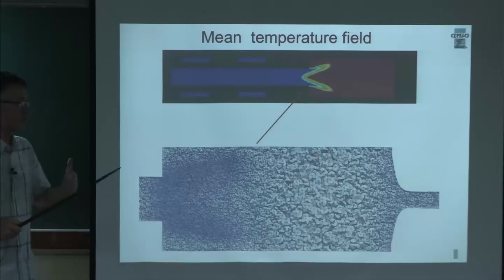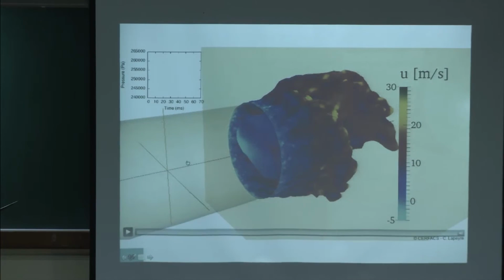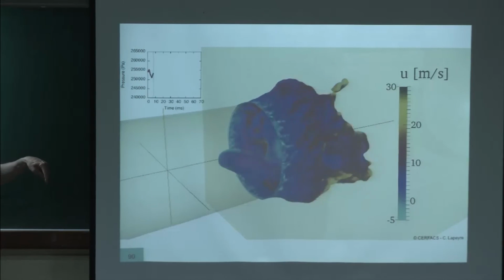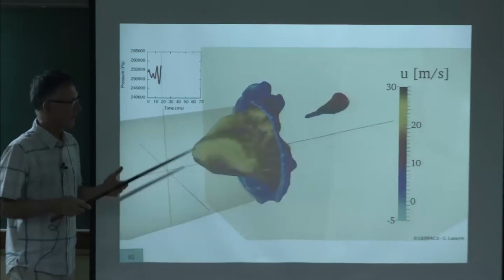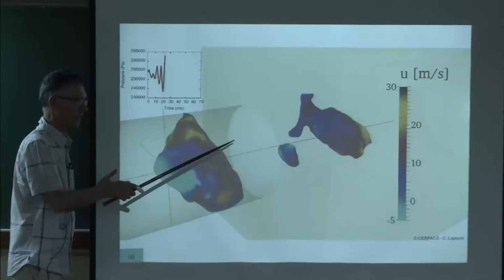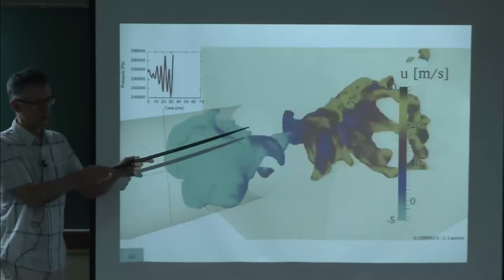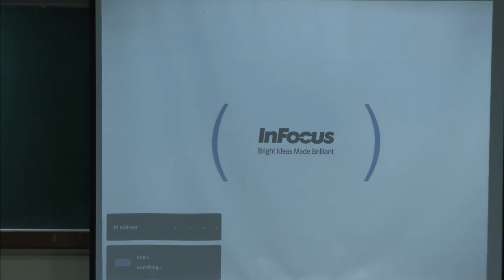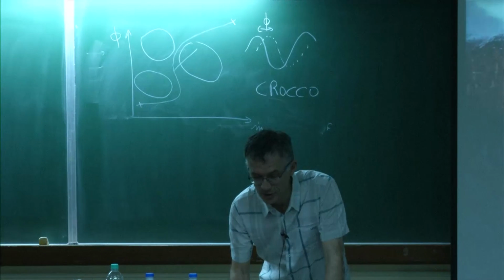But you're right, there is a problem of initial point. Actually, when they did the experiment, what happened is that they would start the experiment, and after a few seconds, they would see that the temperature here in the duct was going to 1200 K, and they had to stop it. So we did not have access to the exact methodology, to the exact sequence which leads to flashback. The only thing we can say is that there is no stable point here. As soon as you put the nozzle, the flame flashes back. So that's another thing which may happen when you have this type of instabilities: quenching, flashback, vibrations, all these things that you don't want to have normally.